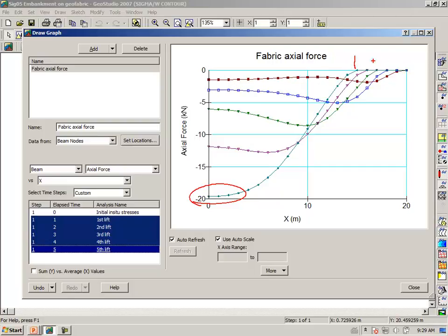But once again, notice that in this area here, the tensile force in the Geo Fabric is 0. In essence, the ground has settled in such a way that the force on the Geo Fabric is compression, and since the Geo Fabric cannot withstand any compression, then we simply set the force equal to 0 because of the edit box that we checked when we defined the properties of the Geo Fabric.